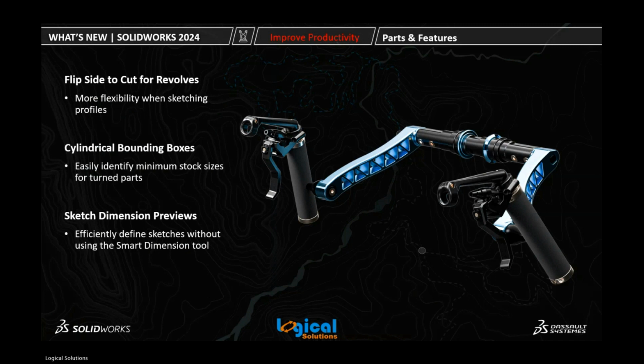And moving on to the next update, sketch dimension preview. We can preview the sketch dimensions when we select a sketch entity. Not only that, we can also select that preview dimension to edit it. Let us see in the SOLIDWORKS. So let me open SOLIDWORKS.